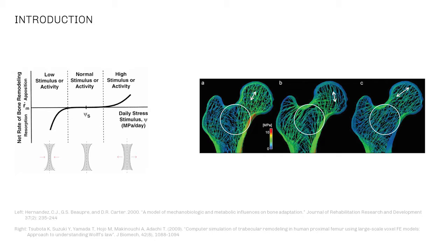Inhomogeneity and anisotropy are favored in natural load-bearing structures, such as a bone's trabecular lattice, and serve to achieve lightweight and high mechanical performance. Within the context of bone's trabecular lattice, responsive inhomogeneity occurs as a result of thickening and thinning of trabecular struts in relation to high and low stress stimuli. Anisotropy occurs through the trabecular orientations being parallel to the direction of pertinent compressive forces.